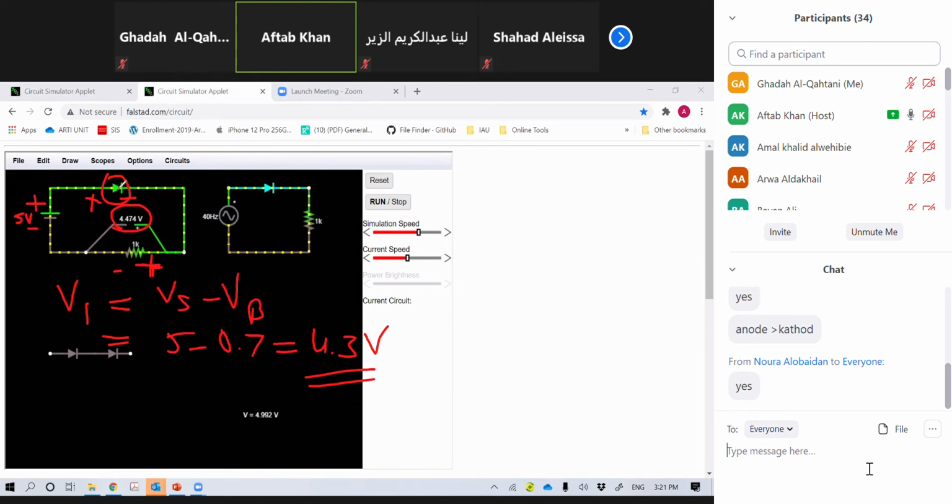All right. Now, if you have any question in your mind, just let me know so I can draw it, or you can try yourself. So this is clear to you? A diode can work as a switch. How does a switch work? If I am saying it can work as a switch, switch means on and off. On means the diode is in forward bias, it is conducting. Off means the diode is in reverse bias, it is not conducting. This is the point, right?